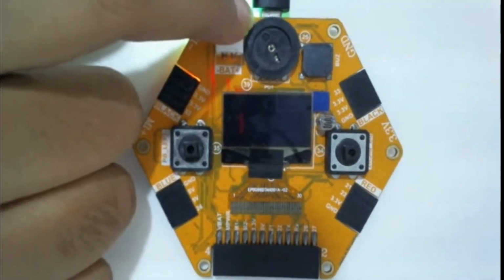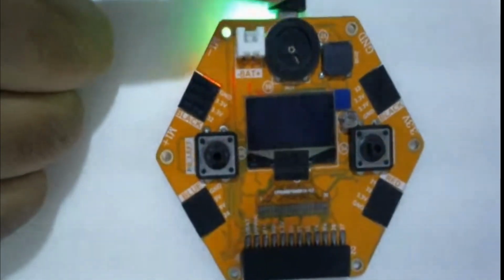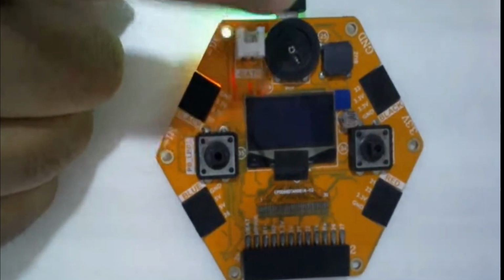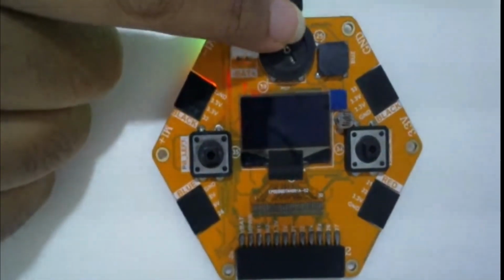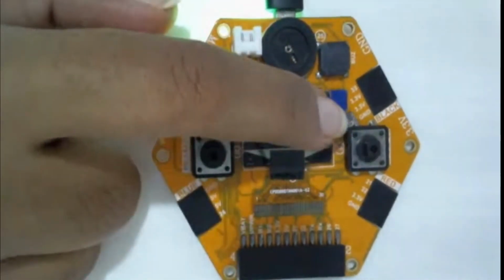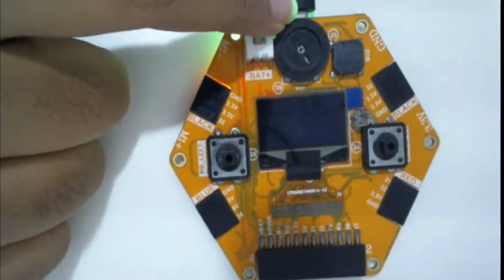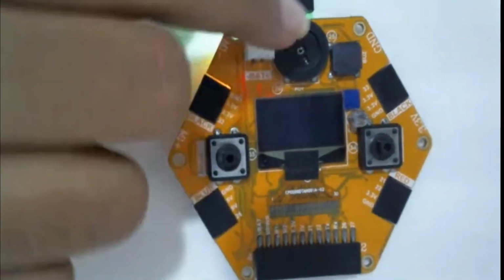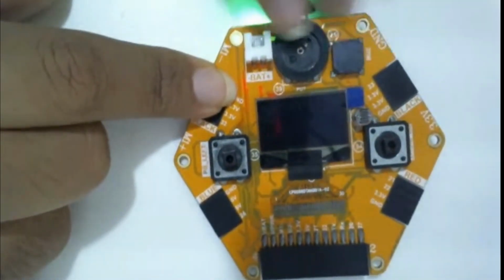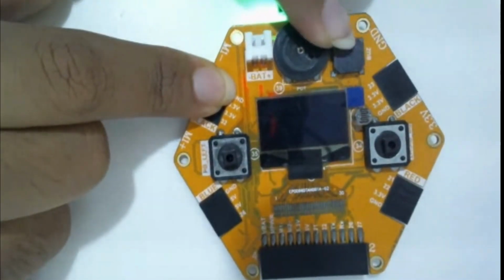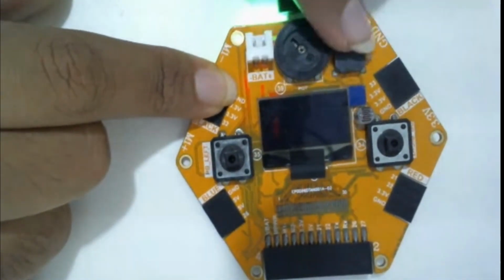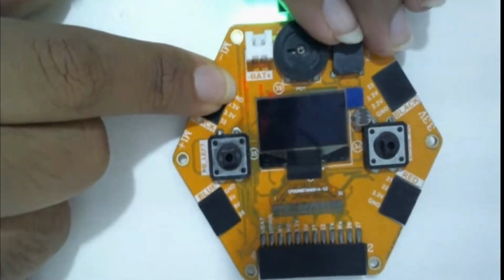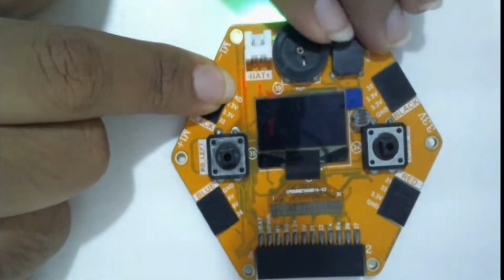Actually, it is not a sensor, it is a resistor, a variable resistor. When we rotate this black wheel, the amount of resistance given to the circuit will change. So the value that we can get from this variable resistor, the potentiometer, has the same range as the LDR, that is 0 to 4096. When we rotate the potentiometer, it starts from 0. Now it is at 0. When we rotate it in the clockwise direction, it will increase the value up to 4096. And when we rotate it back in the anti-clockwise direction, it decreases the value again to 0 from 4096.